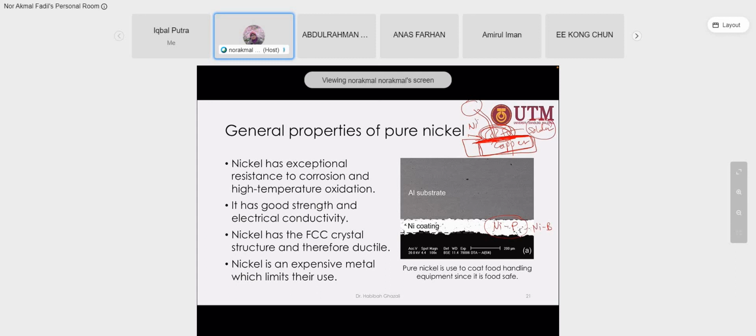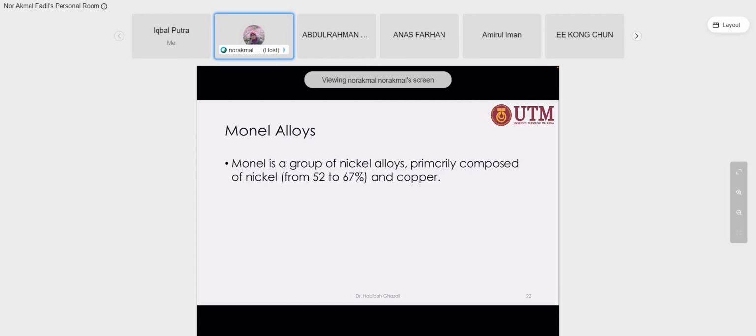So most of the copper substrate is covered by nickel to further enhance the reliability of the joining for the electronic component. So it's quite a normal application of nickel as pure nickel, nickel phosphorus or nickel boron for a coating application rather than as a bulk material. However, there are exceptions for some kinds of nickel alloy. We call it a super alloy.